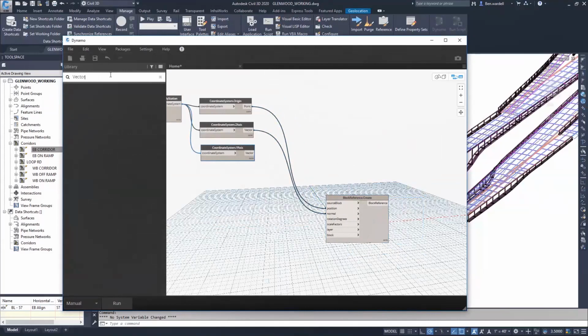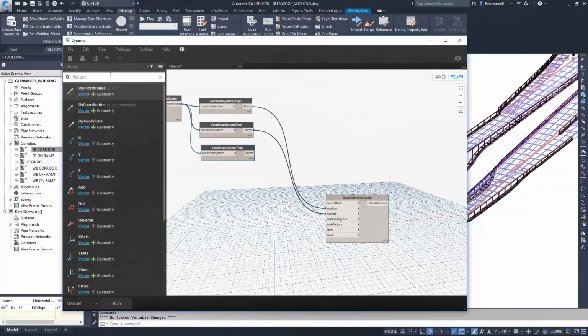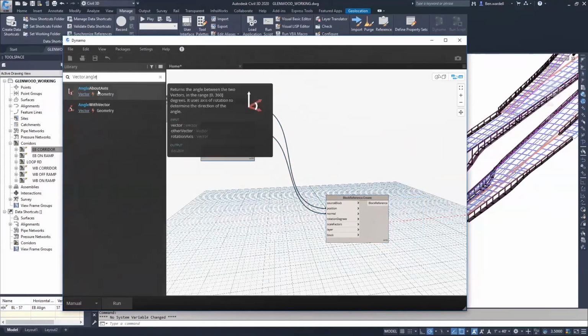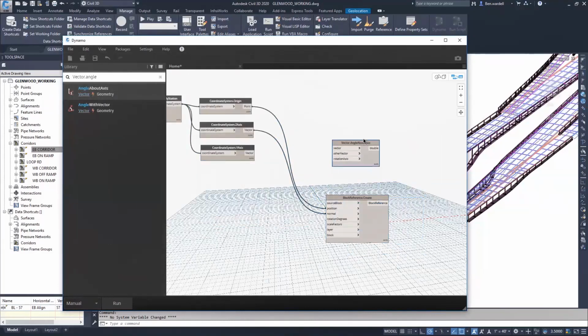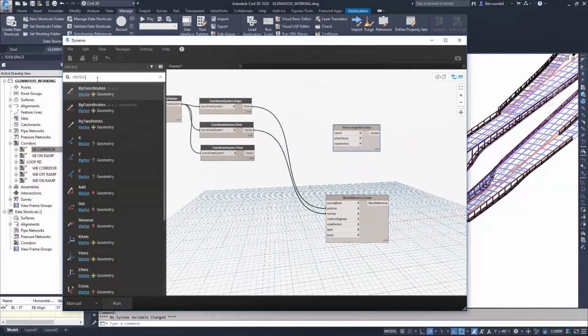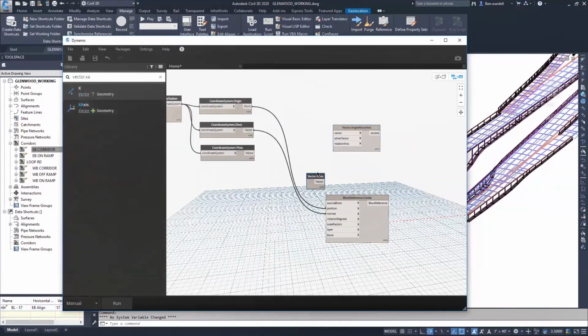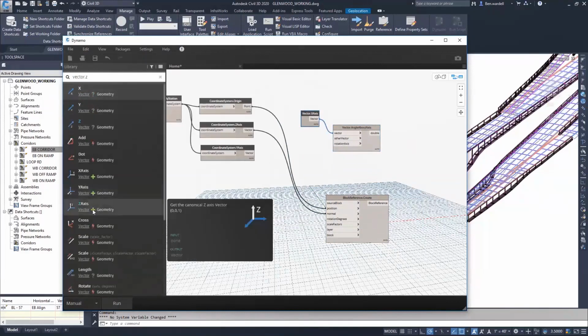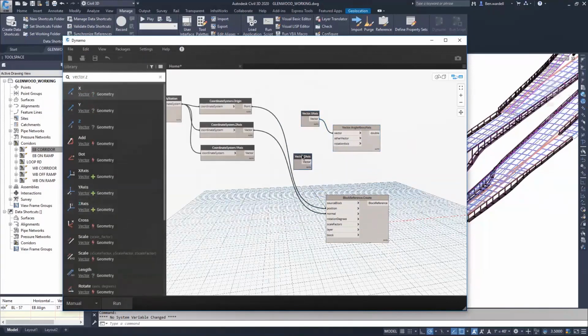In terms of coordination, it's going to be a vector for Z, vector for Y, vector for X, allowing you to change how high or how tall my street lights should be. That's in terms of Z. But the X and Y will be controlling the gap or the diameter or the corresponding size of the street light that you are doing. So that's basically how Dynamo works.